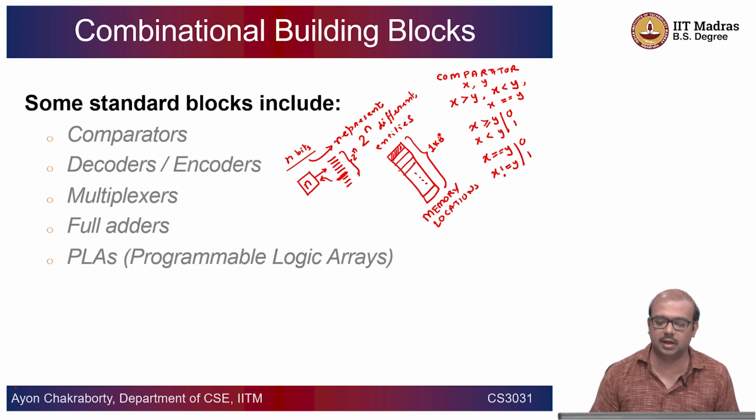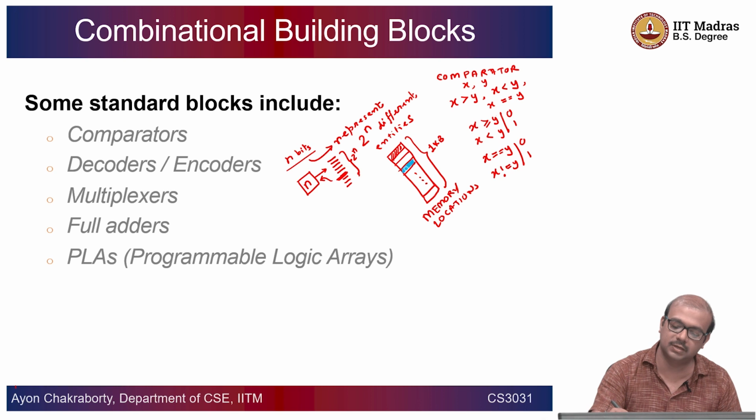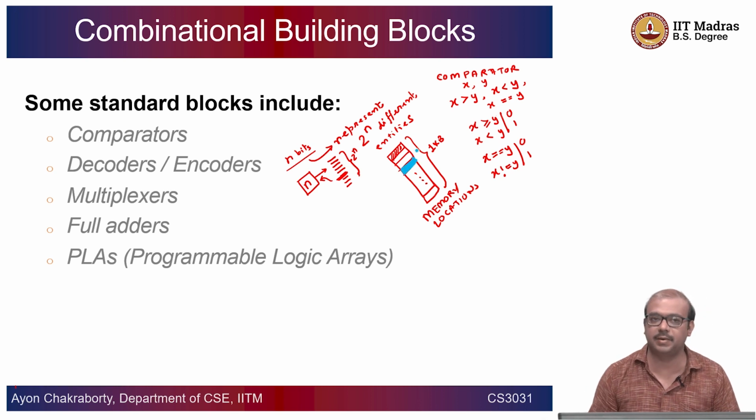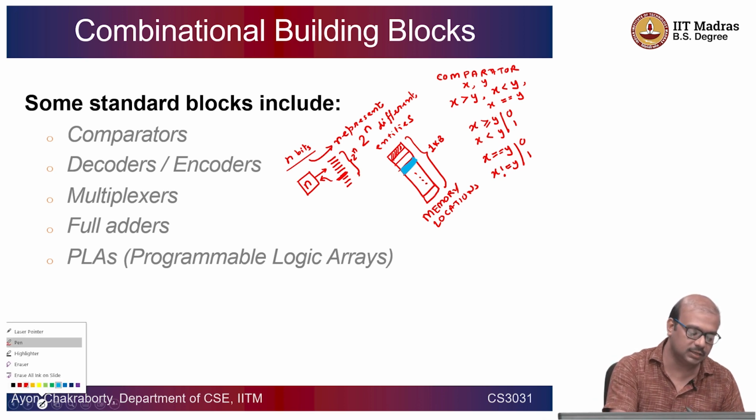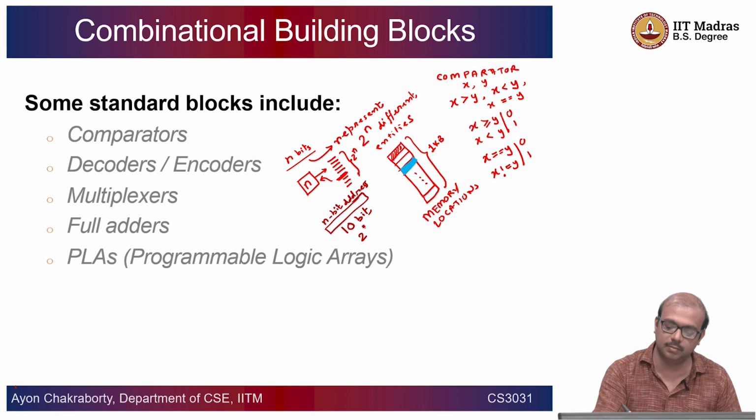because you need to read the data. We often say we want to initialize pointers, and we want to read from that particular pointer, we want to write, and all these things. For doing this, you need to refer to a particular cell here. Suppose you want to read from this blue cell. This is going to have a certain address. So, what the circuit will do is take your n bit address, which is going to be a 10 bit address, because you are going to have 1024 different possibilities, which is 2 to the power 10, equal to 1024. With this n bit address, you can select any one of these, and given a particular 10 bit address, it can be used to choose this.